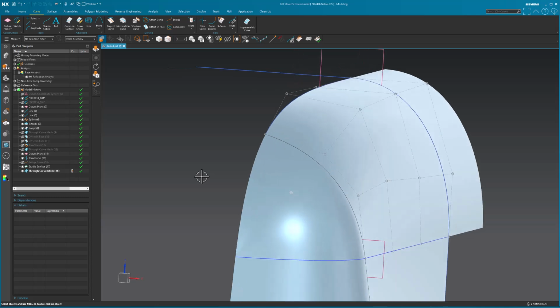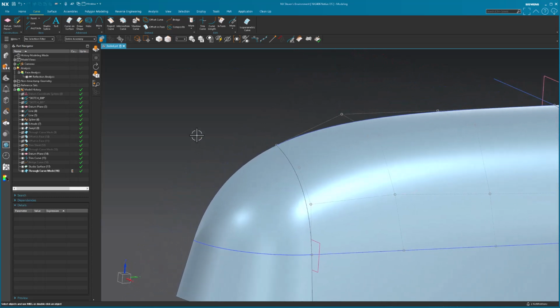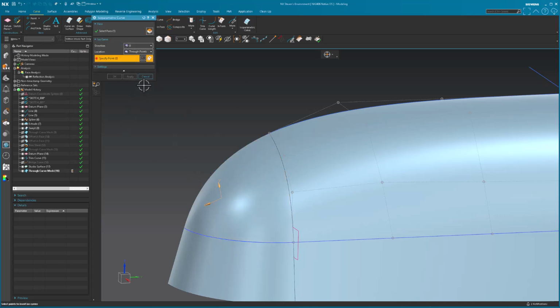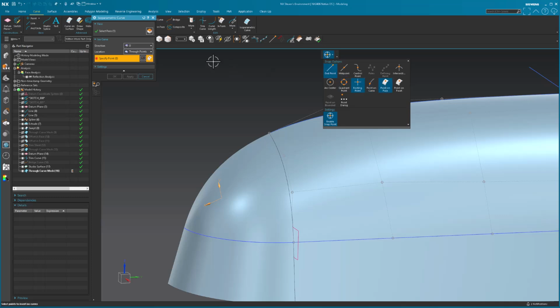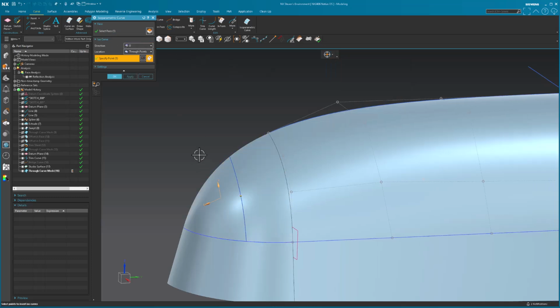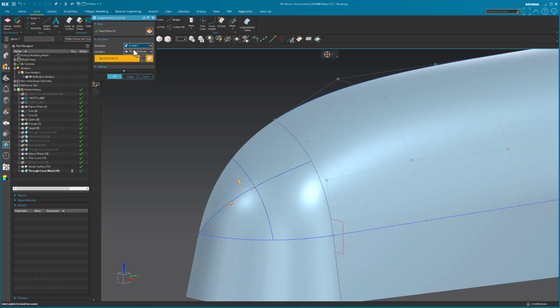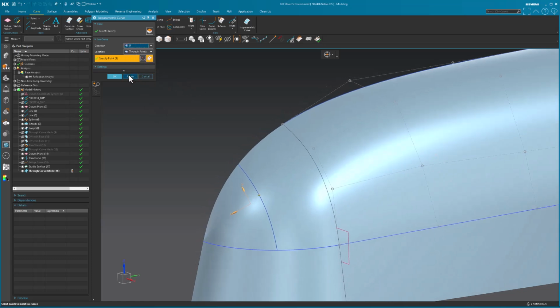Now, what I like to do in instances like this is go in. Now, I'll play around with isoparametric curves, for example. I'm going to put an isoparametric curve on that surface. Let me go point on face. Let me go U and V. So as you can see, this runs up to this point. So it's acting almost as a rotation, which is not what we want. We really don't want that. Okay, so I'll just go back to U, hit apply,